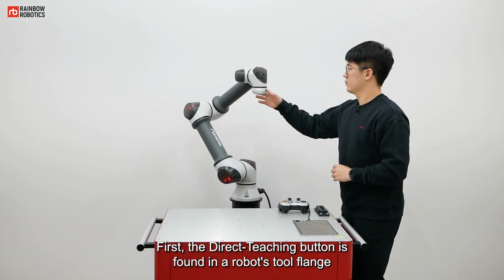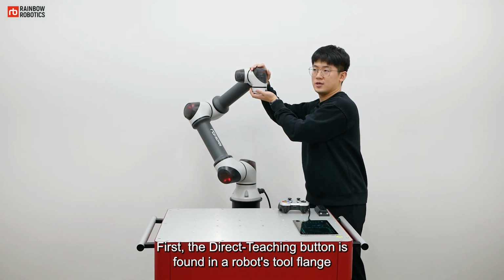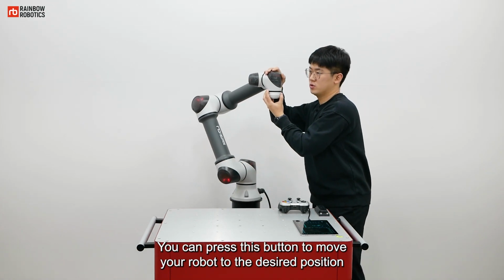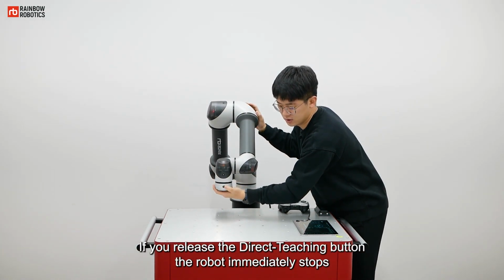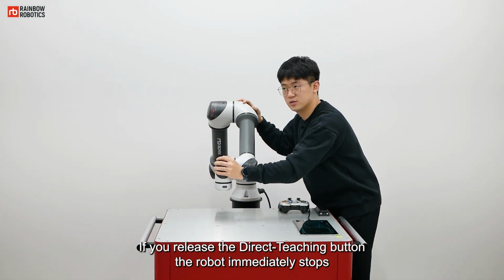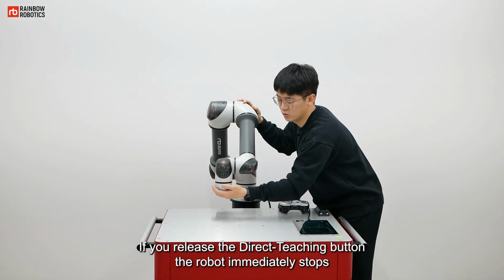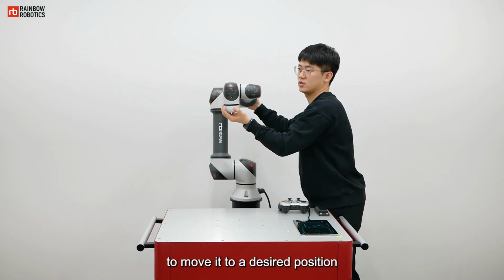First, the direct teaching button is found in a robot's tool flange. You can press this button to move your robot to the desired position. If you release the direct teaching button, the robot immediately stops. Now, you can press it again to move it to a desired position.